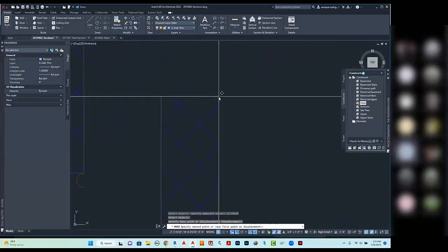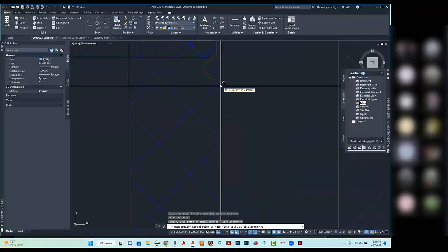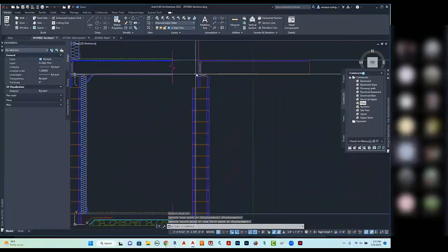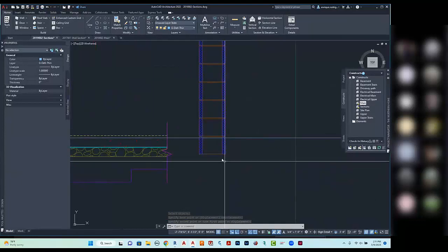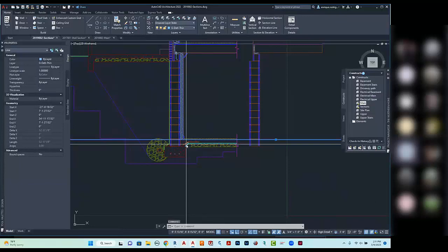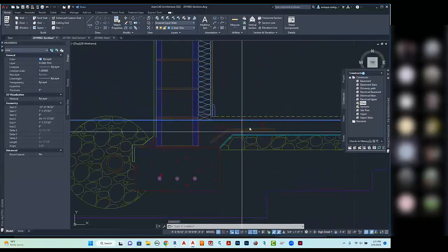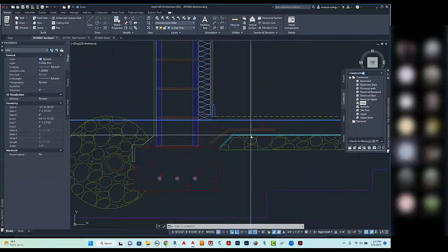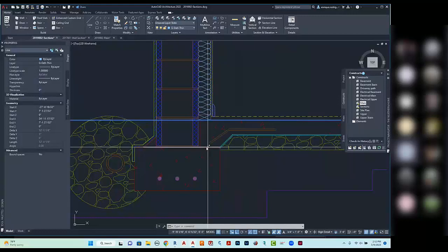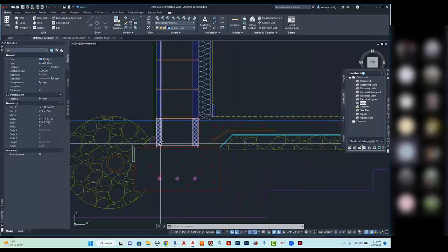Make sure that this point right here ends up with the end point of the mortar. And that's created the ledge. And you notice we've come a little bit below our slab. That's actually where we want to be, because what we're going to do is draw a 4-inch thick slab in here on 4-inch gravel. And there's a slight haunch in here. It thickens up right where it rests on the footer.